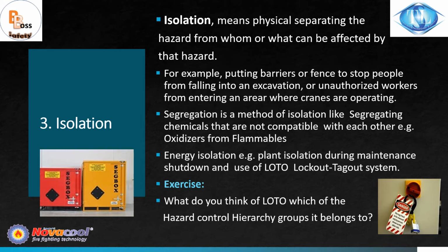So also energy isolation using lockout and tag out, right? We can also look at lockout and tag out as a design and administrative control. So the lock being a design and the tag being administrative, so the LOTO.